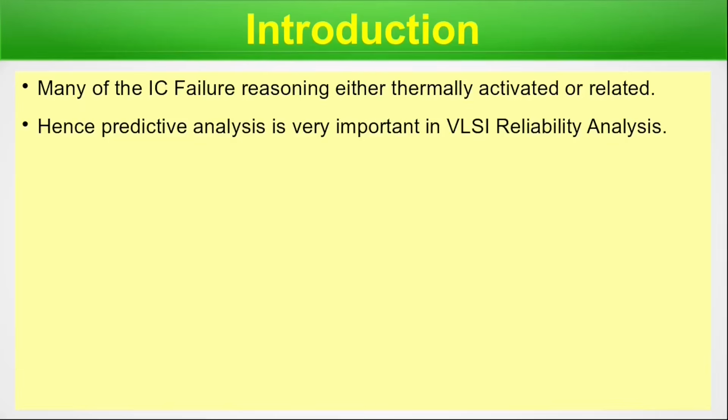Predictive means we use mathematical models inside the simulator, and hence we predict how long this particular chip will run before it fails completely or before significant damage occurs. This is the importance of the predictive analysis. When we do this predictive analysis in the physical verification stage, we take the help of tools that are able to judge the long-term effect of electromigration and can detect which and where these failures may come. Accordingly, we take corrective actions so that we can mitigate the effects.